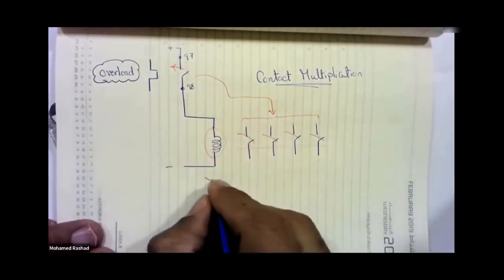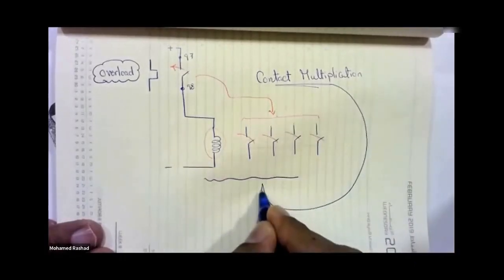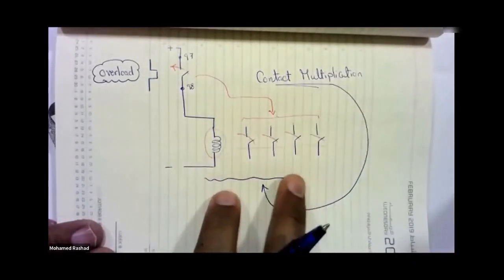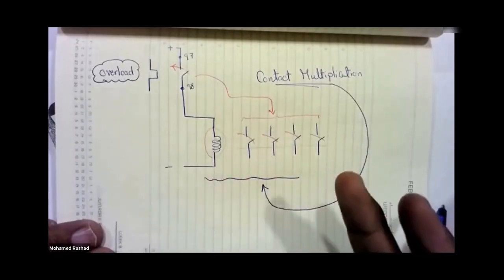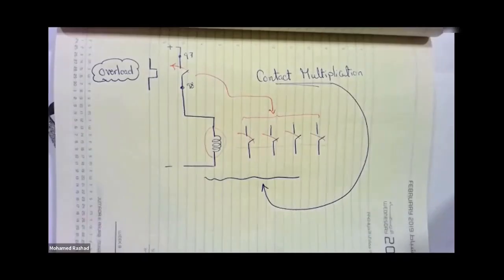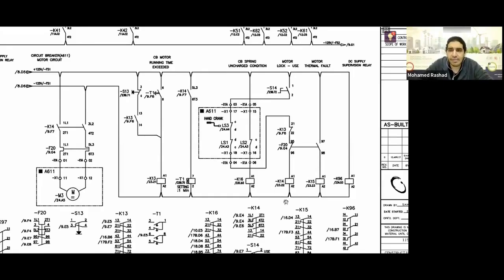So in this case, our auxiliary relay is used as something called what? Contact multiplication. And this is the second use of the auxiliary relay that we've seen now, apart from the AC supervision that we saw in our AC circuit. All right, guys, great. So now it's telling you that with the action you did when you activated K15, look down here, there's K15.